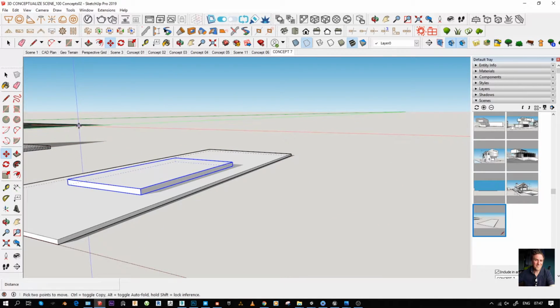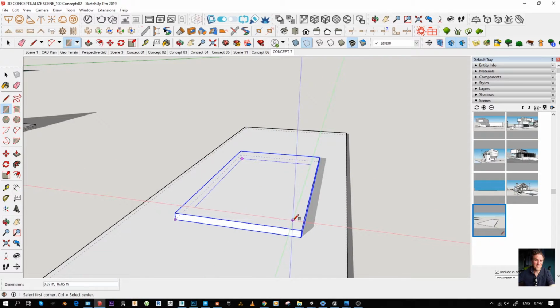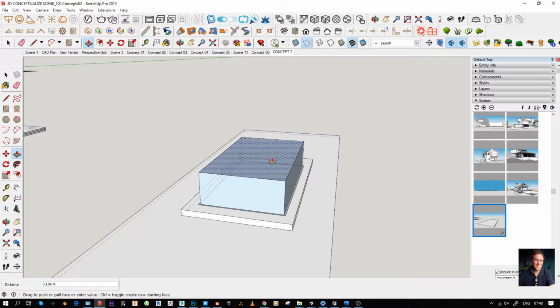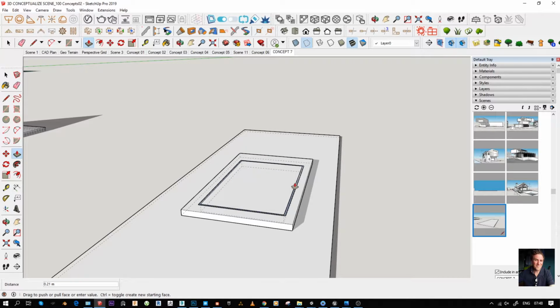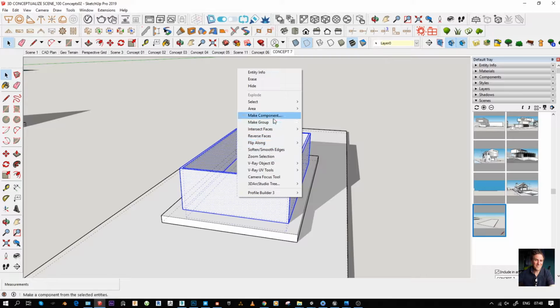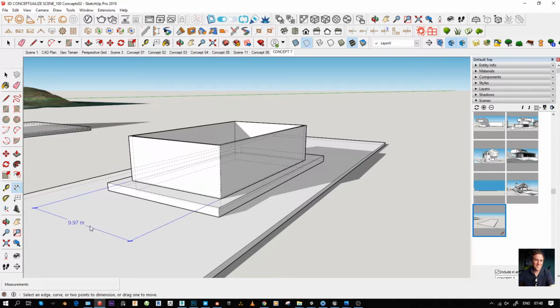And then if you want to start building, say on top, just very quickly the walls, you would offset like so, and you can type in 0.2, and you set it for 200 millimeters or 20 centimeters, and you've got the wall. You can just loft it in place. When you loft your wall in place, if you triple click, again, it's all about creating groups and components inside of SketchUp. So each time you create something, you create your group, and then you're setting up your dimensions, which you can rescale down to whatever dimension you want. So basically, SketchUp is very useful for 3D sketching.